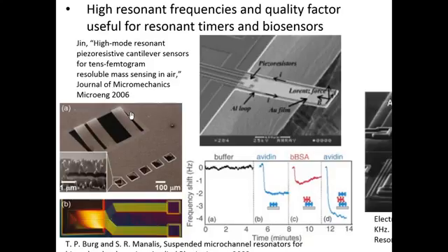So what you would do is take this type of biosensor that's coated with an antibody specific to the protein that you're looking for, and you just dip it into your sample, right? Those proteins attach to it, and that changes the mass of the cantilever. Now you take your cantilever out of the solution, you remeasure its resonant frequency, and now you have a different resonant frequency.